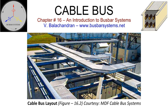Cable bus connections are more flexible and easier to negotiate at the site, which lends itself easily to modification at the site to cater to mismatch or misalignment. Cable bus can run in trenches and avoid right-of-way. Transposition is not required to minimize voltage unbalance and voltage drop, as it can be achieved by cable configuration, interleaving. Compared to a bus duct, a cable bus has a shorter lead time to manufacture and deliver at the site. A cable bus has a much higher current rating than the same number of cables laid in a tray or a conduit.